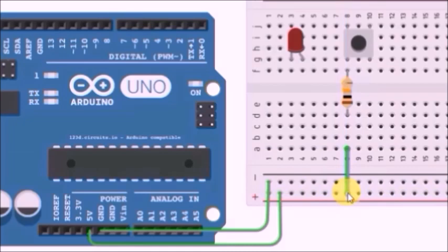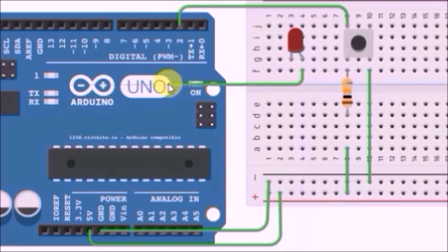For this step, we connect everything in pull up. But this time, we're going to link the output of the button with the pin number 2 of the Arduino board. Next, we are going to connect our LED to the pin number 3 of the Arduino board. Now we are going to change a little bit the colors in order to be able to observe the process.